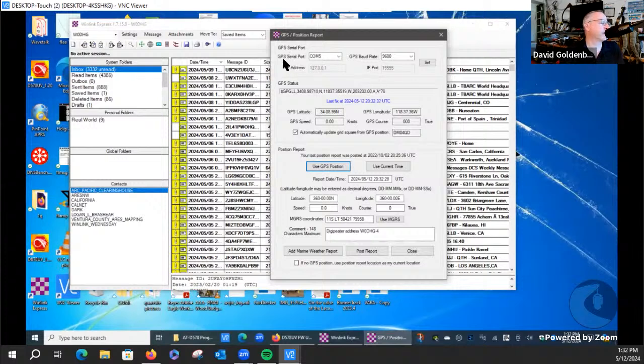And right here, it's going to go right into what's the serial port. As you can see, it found it because I've used it before, and it's set for COM5, as well as the port speed. Again, in the device manager, you can adjust that as needed. If you see the device in the device manager and it shows up with a COM port, it may have picked a different COM port here.